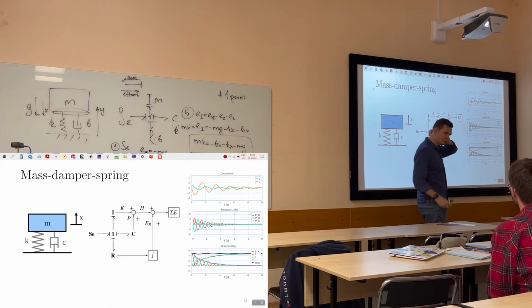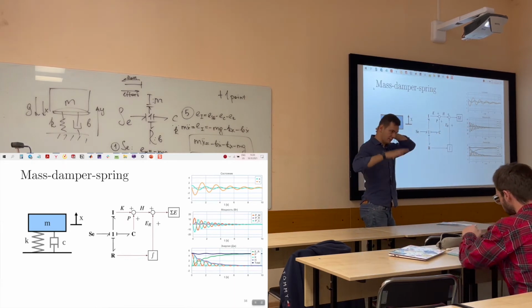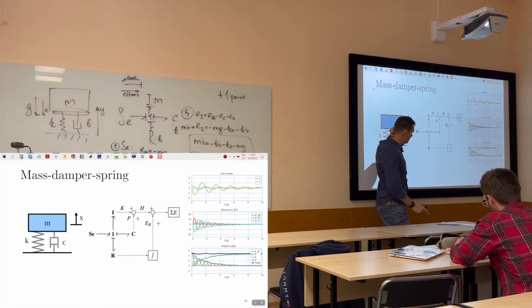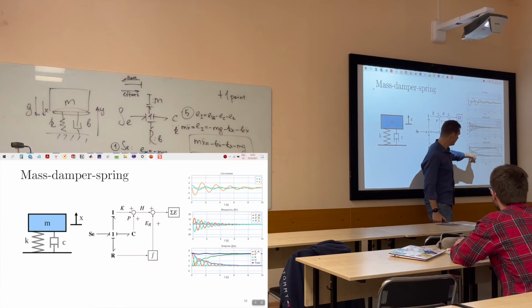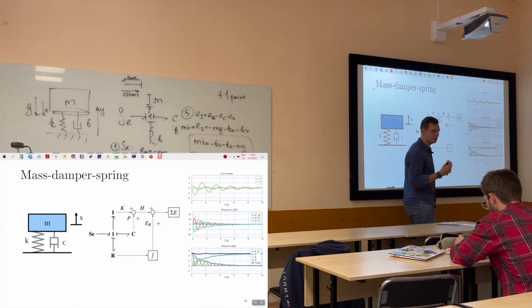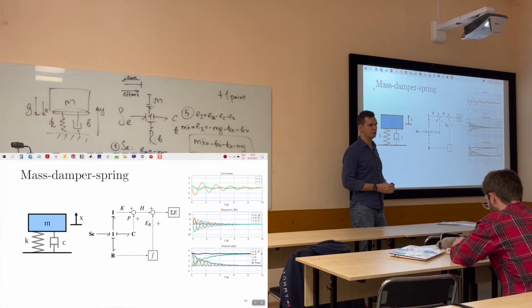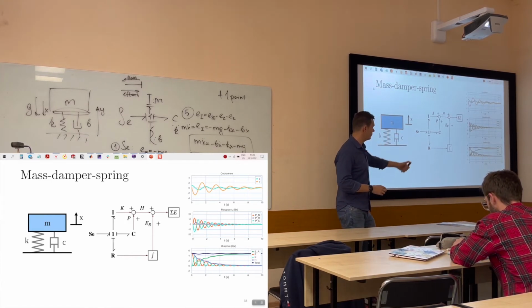And if you want to create a robot that oscillates and the amplitude is constant, you actually need to create a system that will keep the Hamiltonian constant. So you need to calculate how much energy you lost and make an energy efficient controller that just compensates all the energy that you lost in your damper.